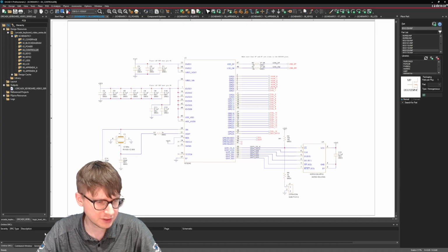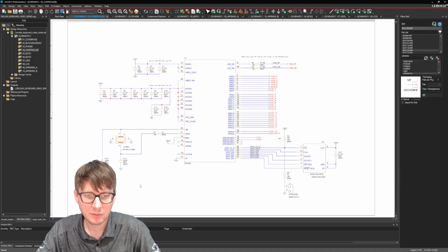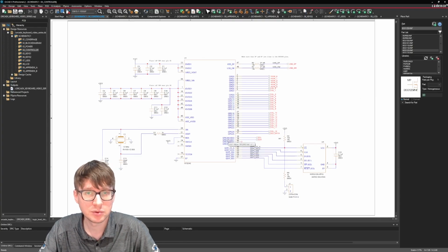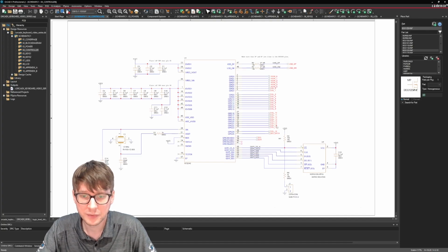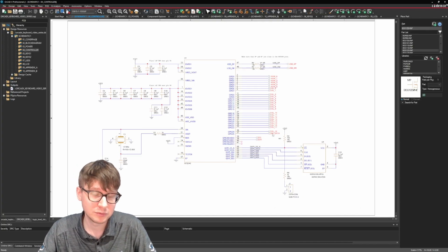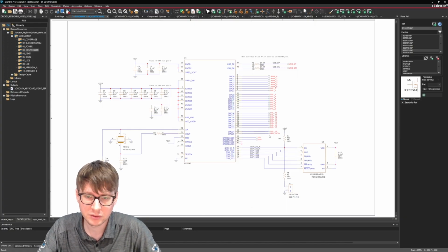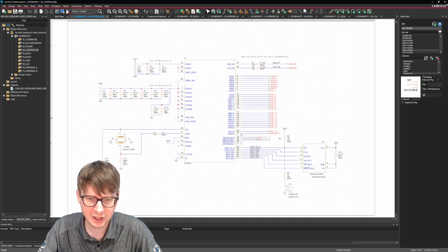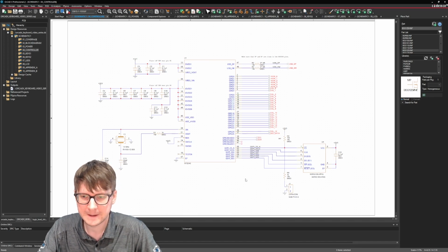I don't see any warnings in my DRC, which is always a good sign. One thing I'm going to do off stream really quick is I'm just going to double check on each of these pins to make sure that, you know, this GPIO 26 and 27 are actually compatible with running my I²C interface. But otherwise, everything else should just be your general GPIO. The rows and columns are either going to be toggled high or low, or will be configured as an input and reading either high or low. And then the LED data is just a simple digital signal output. And a GPIO pin should be able to handle that. And then finally, like I said, I'll double check SDA SCL.